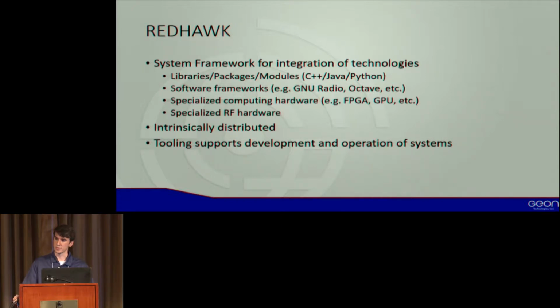It supports multiple frameworks. Like we saw from Thomas yesterday, you can integrate with GNU Radio. Octave, not necessarily a framework, but a free open source alternative to MATLAB you can use for prototyping your DSP. And you can actually wrap that in a REDHAWK component and run it in your target application, essentially. It'll be slow, but it'll allow you to get a good idea of how things are going to work.